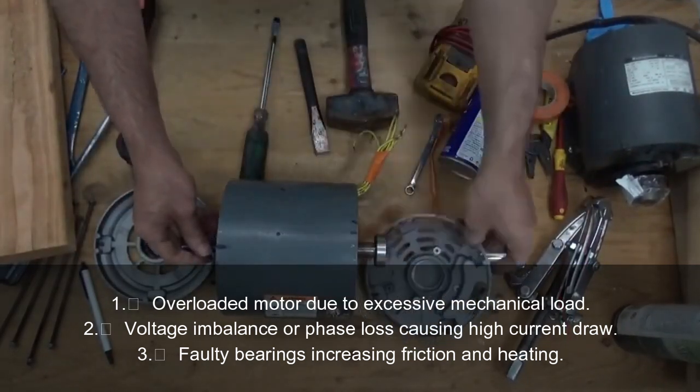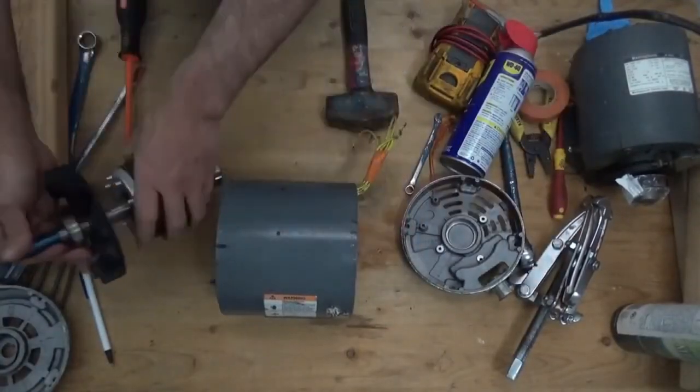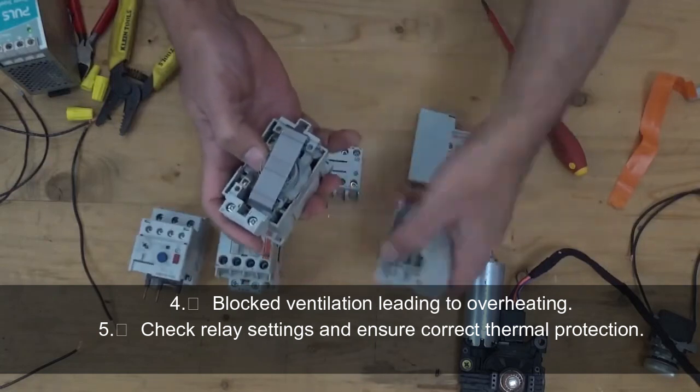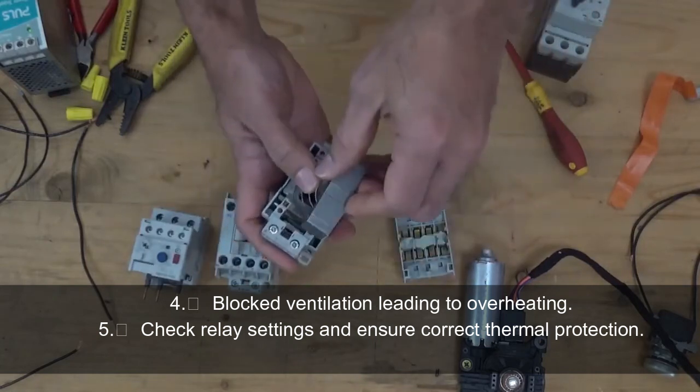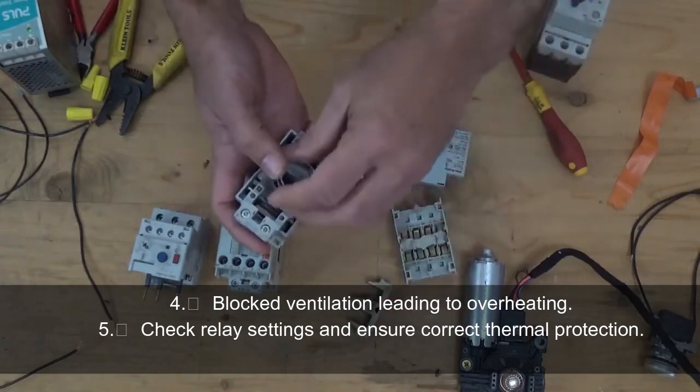Number 3. Faulty bearings increasing friction and heating. Number 4. Blocked ventilation leading to overheating. And number 5, check relay settings to ensure correct thermal protection.